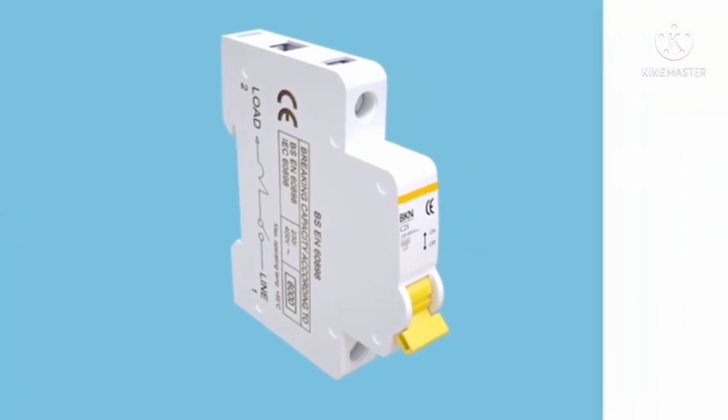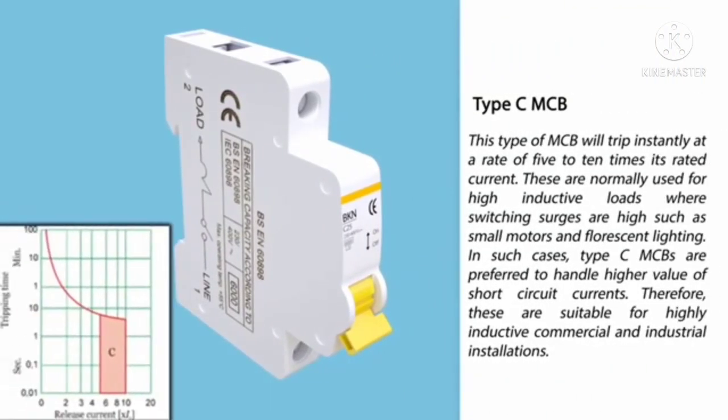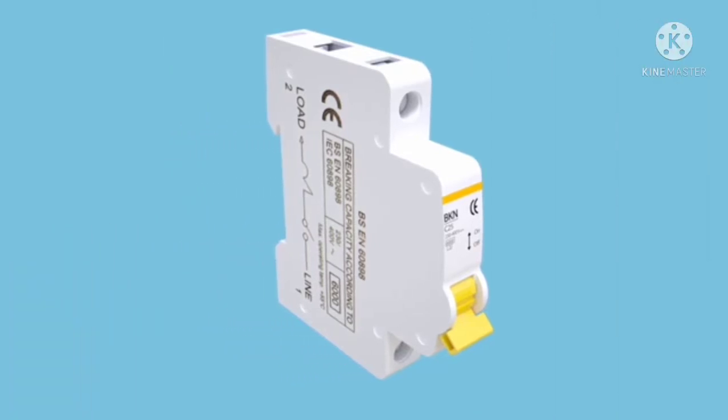Okay, and the next type is type C. This type of MCB will trip instantly at 5 to 10 times its rated current. These are normally used for highly inductive loads where switching surges are high, such as small motors and fluorescent lighting. In such cases, type C MCBs are preferred to handle higher values of short circuit current. Therefore, these are suitable for highly inductive commercial and industrial installations.